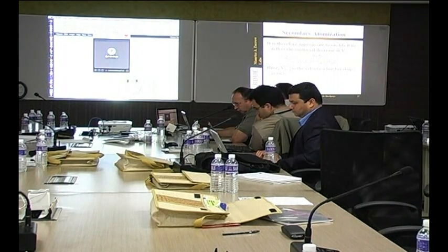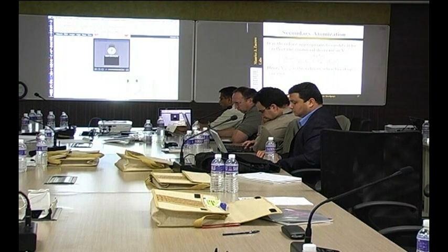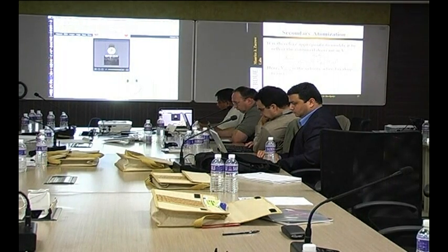The difficulty now is that we have this new unknown, V drop, that needs to be computed, but we have information on how to do that from other work by Pilch and Erdmann. And so we can actually take the total breakup time, insert that back into correlations for the drop speed at the end of breakup, calculate the maximum diameter, and use that then to estimate or to provide information about the fragment size distribution.